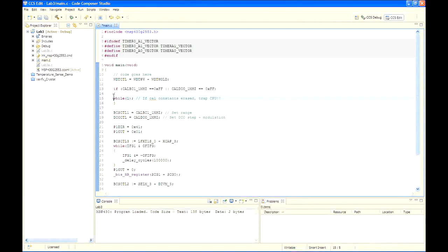Blank flash memory reads as FF. Plugging FF into the calibration of the DCO would be a real mistake. It's not going to run anything near what you expect it to run. You might want to implement something similar to this in your own fault handling code, but obviously a trap like this would probably not be what you wanted to do in production.